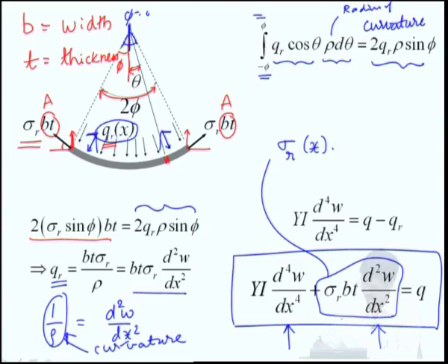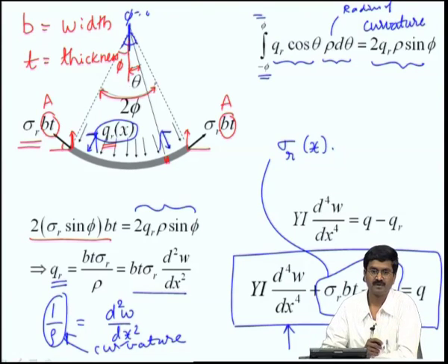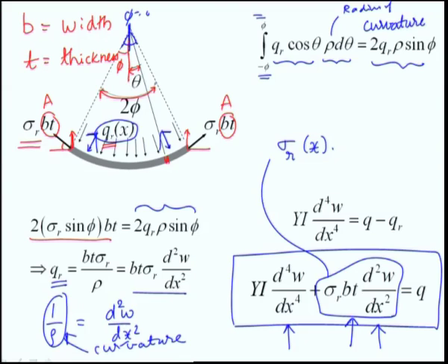So, many of the physical or chemical changes that happen in a material would cause residual stress. All of those now can be dealt with in the context of beams by adding this term. In a general case also a similar term will come, and that can be discussed when we come to the general form of elastic deformation equations. Right now we only talked about, in the last one of the earlier lectures and today, just the axial expansion, contraction and bending of slender structures such as bars and beams.